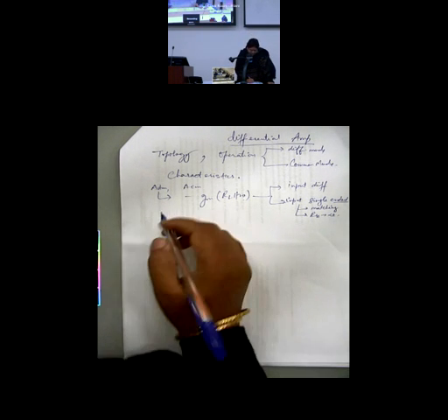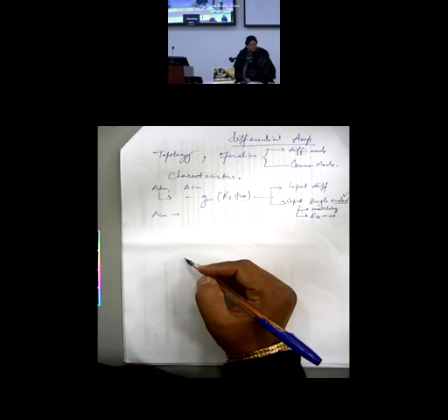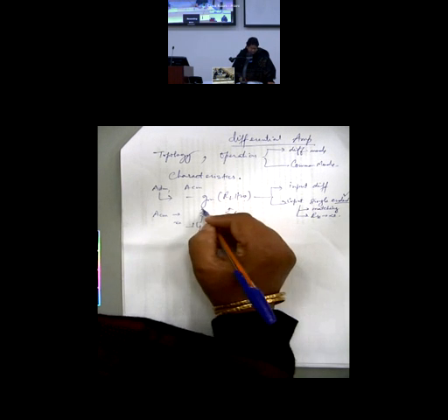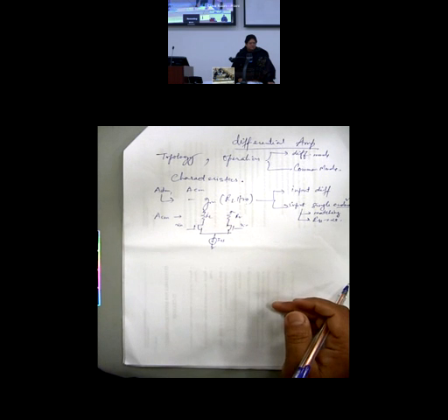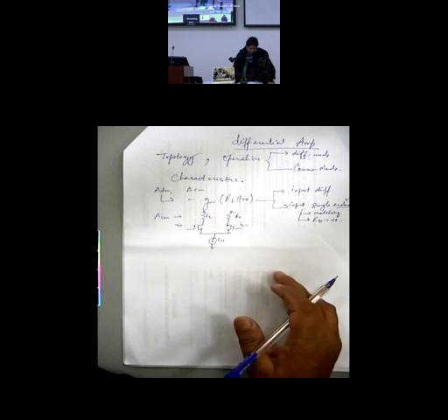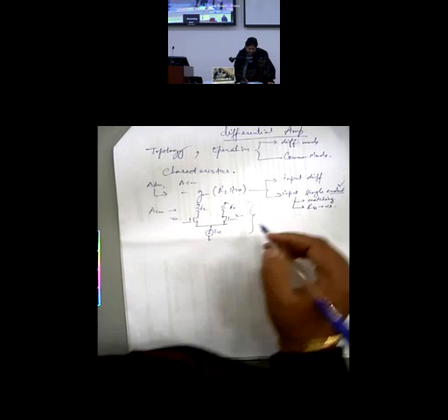As I said, in ACM you have to do ACM analysis, whenever you have an input applied single-endedly. So again, you can draw the circuitry like this. It is ISS over here, this is the input. So Vin is common to both, the same Vin. This is RL, this is RL, RL and RL are matched. So either you can go for the half-circuit concept or you can go for the folding of the circuitry so that one simply coincides with the other. Do the analysis, find out ACM.